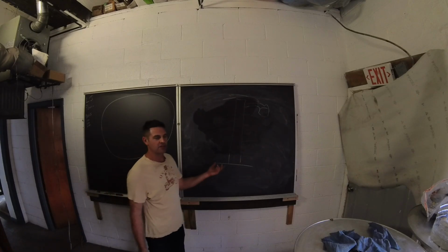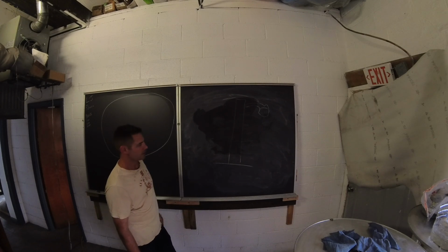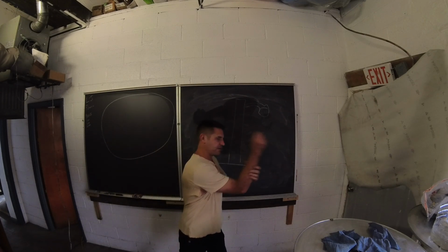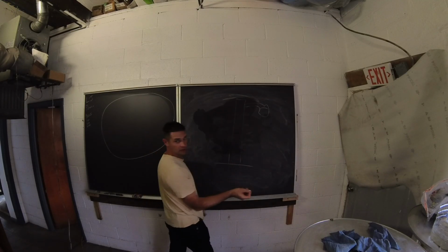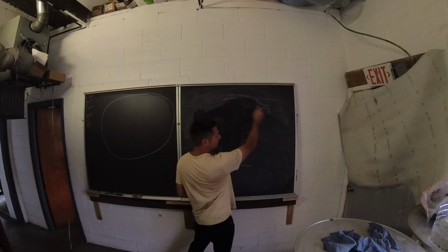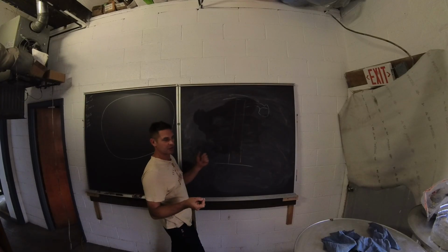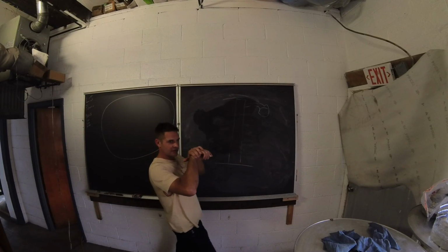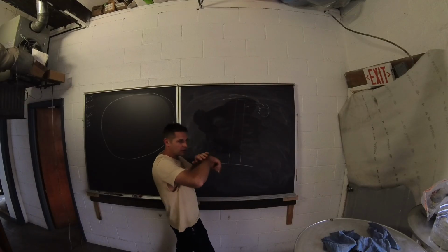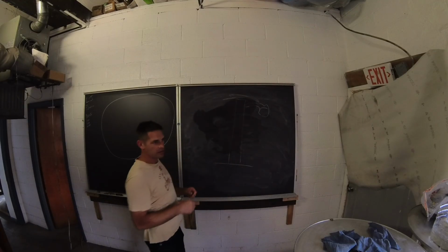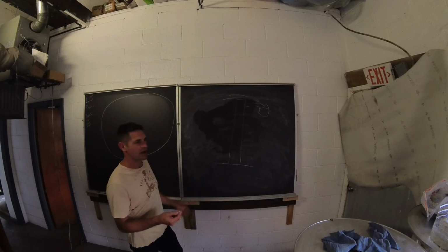A metal spring, at least, has very little damping to it. So if you feed that natural frequency to the spring, just like a tuning fork, you can get it to wobble further and further because there's very little damping. The only damping in a spring is that the material itself has some amount of inherent damping as the little molecules do the little bump and grind, but it's very little. So for all practical purposes, springs don't have damping.